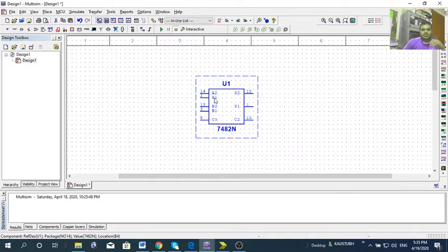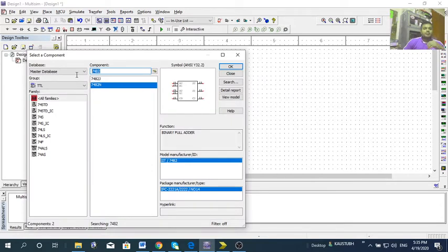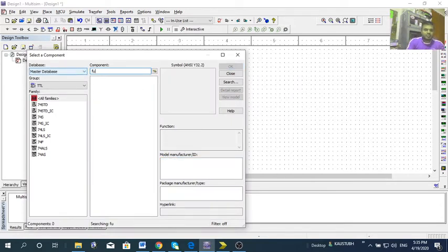One is A1, B1, and C0, then A2, B2, also with C0, and outputs are SUM1, SUM2, and this C2 is the carry for both. Okay. But instead of this there is also another direct full adder block. You can type full adder.